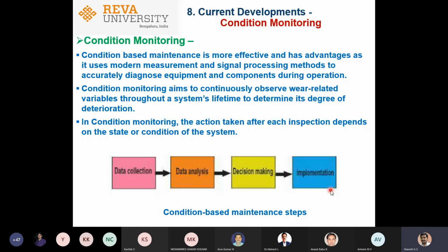Whereas in preventive maintenance, the engines have to be brought down and have to undergo preventive maintenance. Like they have to come at 125 hours, 250 hours, for example, 500, 1,000, 2,000. That many times the engines have to be brought down. So when you bring the engine down several times, you are losing a lot of operational costs. You are losing big business. There would be a lot of delays, cancellations, and all that, for unnecessary maintenance.